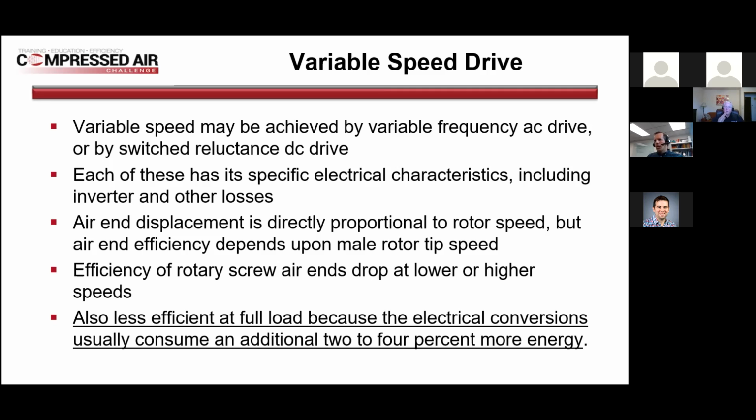So when you start lowering it and using a VSD to go lower, your efficiency just keeps dropping further and further. So it wouldn't be very efficient to do it. The other thing VSDs have is when they get into a low load condition and a low RPM, the manufacturers will actually lock it out because they found there's not enough temperature to boil off the moisture in the oil, and it causes problems with the machines themselves. So it isn't recommended. The other thing you always have to keep in mind with putting in any VFD drive is, depending on the age of the motor, whether it can take the inrush current that happens with a VSD. So again, you can do it, but I wouldn't recommend it.